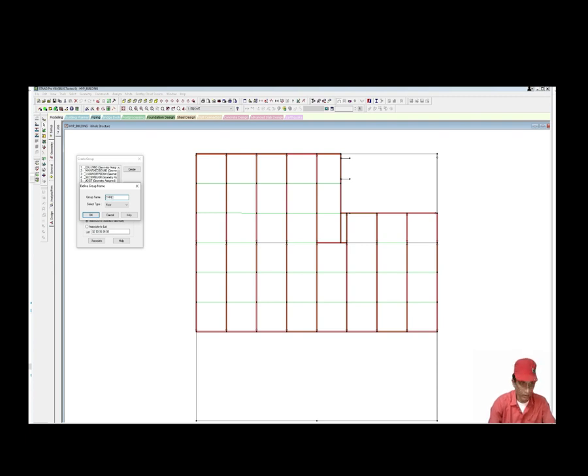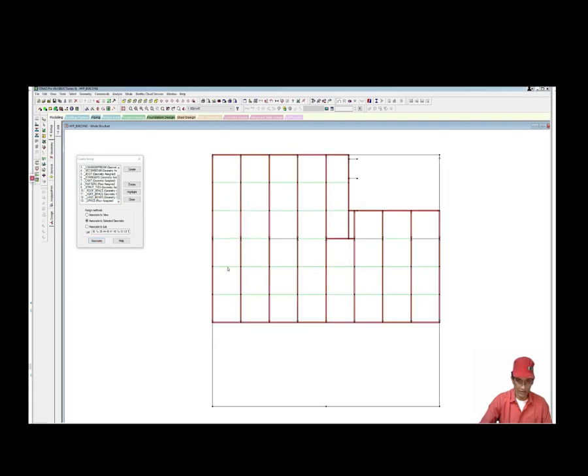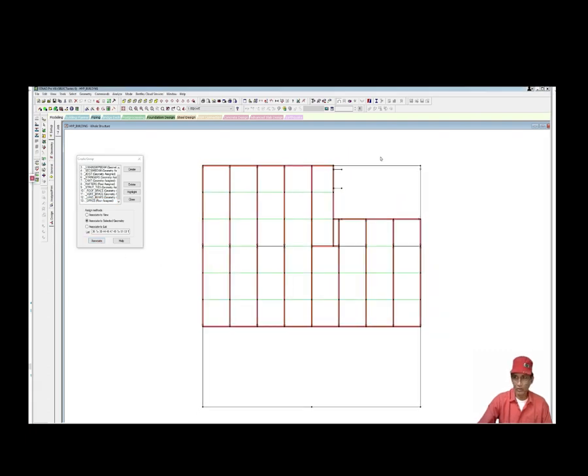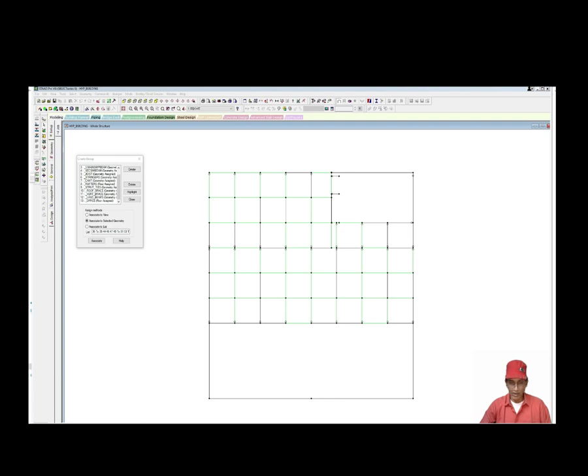office. Okay. Associate to the selected geometry. It is associated now. Next, we shall assign the gravity load at the mezzanine, also at the roof level.